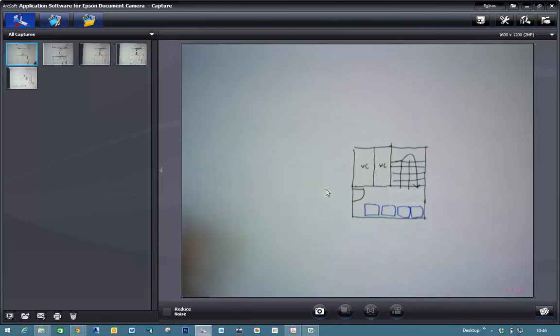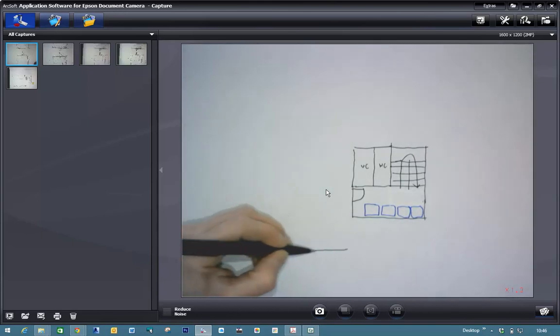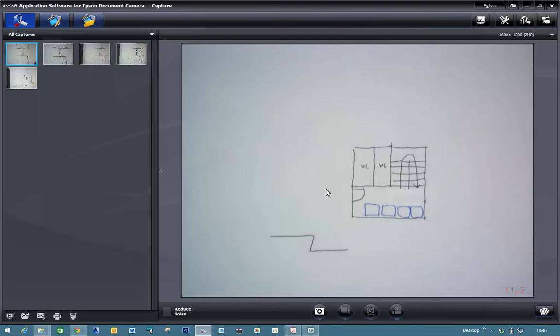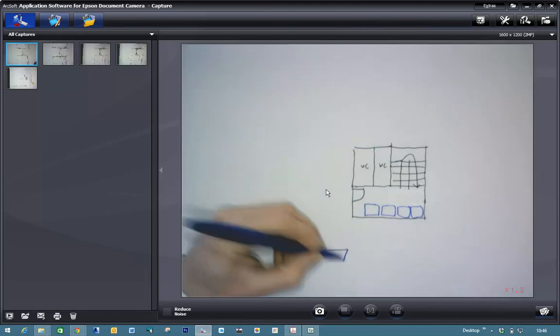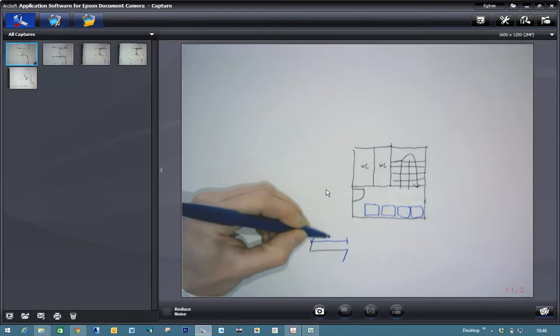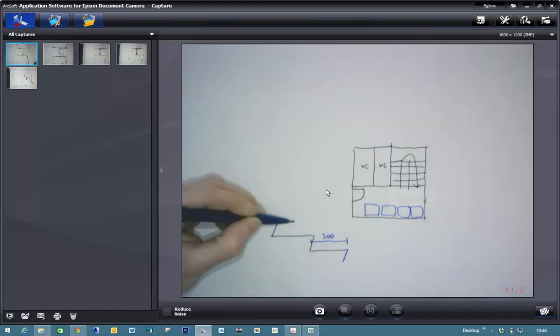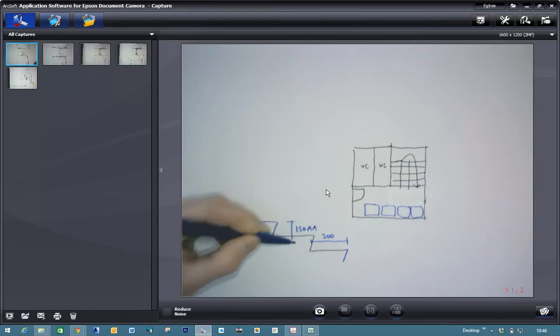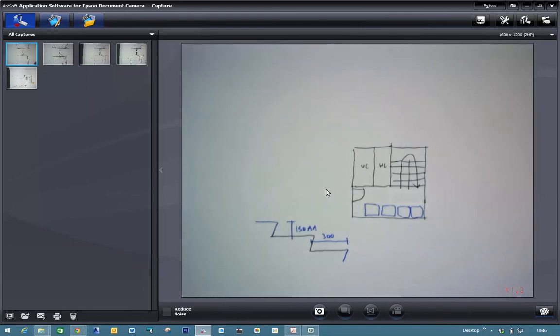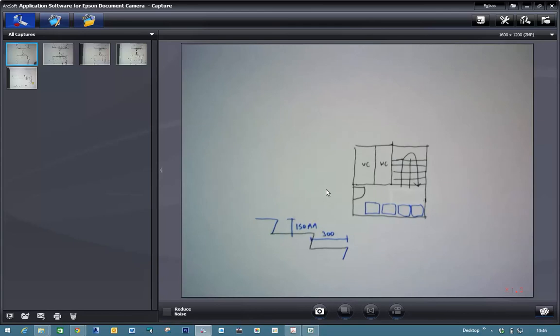I mean, it's not for this week, but just to know that in an accessible stair, you're looking nowadays for a 300 millimeter going and a 150 millimeter rise. All right, that's what you're aiming for now. So they're quite big. Imagine, again, don't think of the Arts Tower. Imagine a stair which is that long, and they're only that high. So you need a lot of those to get you up a story. So these stairs become quite large. Okay, we'll draw that next week.